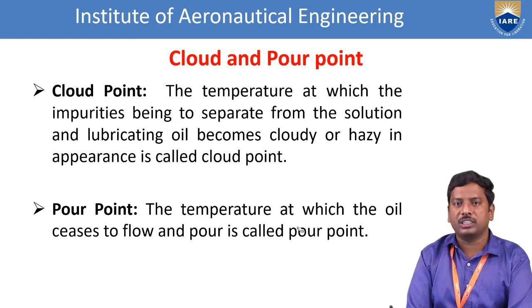So after that we see the second property of lubricants, nothing but cloud and pour point. First of all we see the definition of cloud point: the temperature at which the impurities begin to separate from the solution and the lubricating oil becomes cloudy or hazy in appearance is called the cloud point.